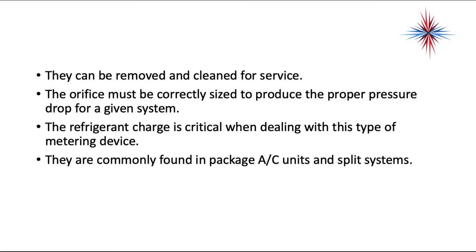The metering orifice can be cleaned and removed. The orifice must be correctly sized to produce the proper pressure drop for a given system. The refrigerant charge is critical when dealing with this type of metering device. These are commonly found in package AC units and split systems.